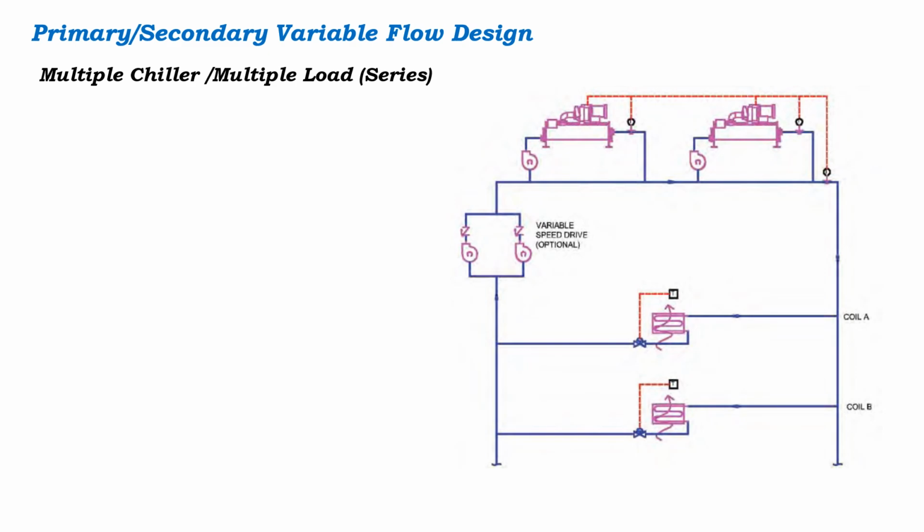If these chillers are configured in the series configuration, here you can see the rest on the load side is going to remain the same, but in the series there is going to be a pump for one chiller and a second pump for the second chiller, and the system is going to pump to the load side, and it is going to be configurable.